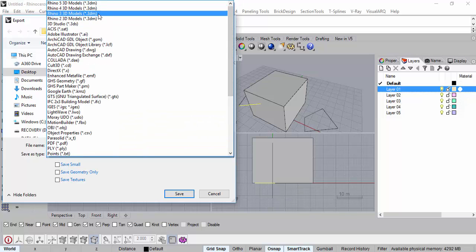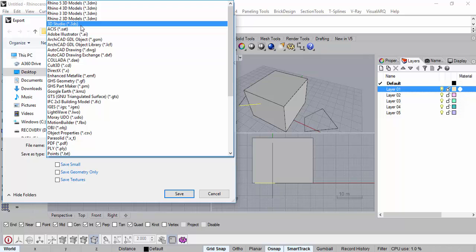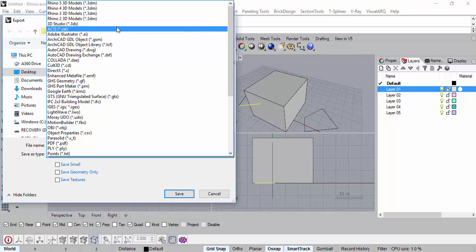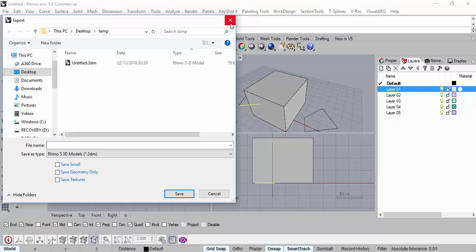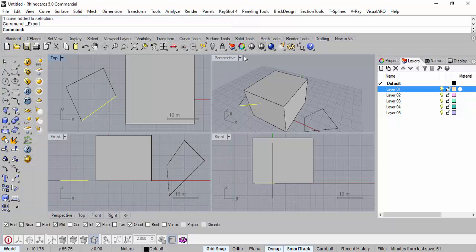And you can save in different versions. You can save it to a Max file also. You can take this into 3ds Max. Why people use Max is because you can really get good rendering quality, that very photorealistic quality. So part of your model can be done in Rhino, which is difficult to do in Max, and then you can continue from there to build in Max, whatever is easy in Max, including the visualizations and renderings. Okay, fine. So this is about the viewport.